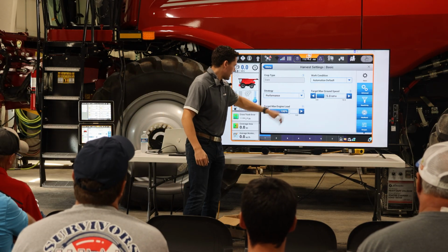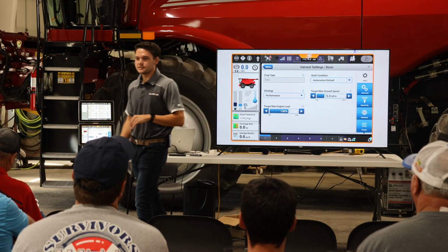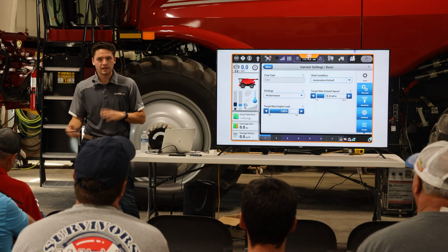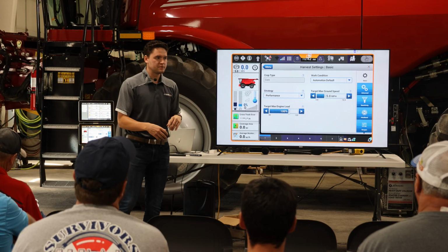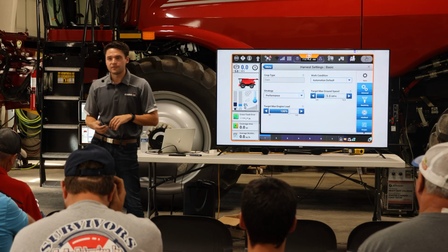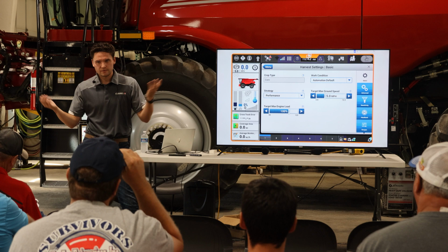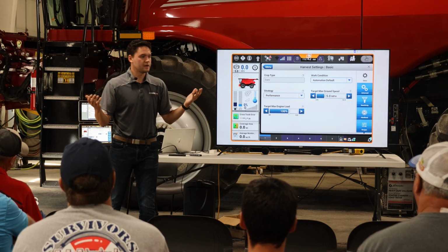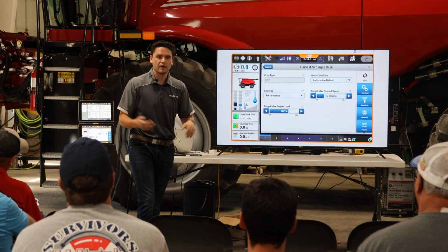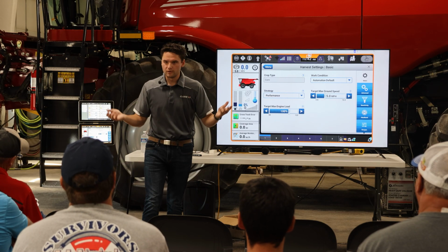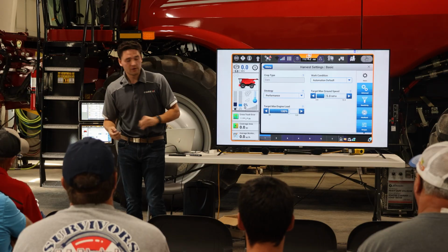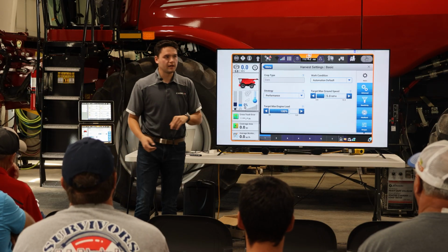And then with our target max engine load, I typically like to see that as close to 100% as we can. Again, we might have a different desired with our different crop types, but preferably no less than 95% because, well, how is my machine more efficient? How do I get the best grain quality out of a rotary machine? Keep it full. Keep it full. And we're going to do that by having our engine load as high as possible.